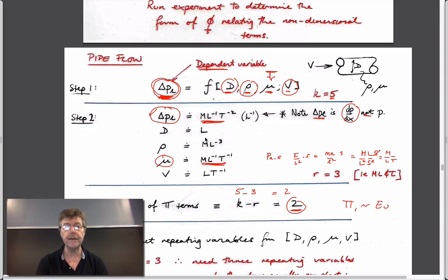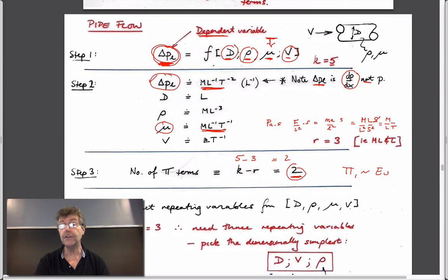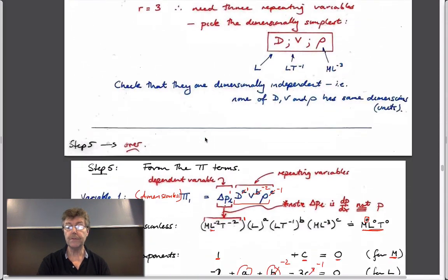So density comes in through that. And so if you can guess what the parameters would be that define your system: some definition of geometry, the diameter of the pipe, the length of the pipe; some definition of the fluid properties, which are density and viscosity in this particular case; and some definition of the response of the system. So the response of the system would be the pressure you have to apply to be able to drive a flow and the velocity you'd get after you've driven it. And so those are the 5 parameters that describe this behavior.